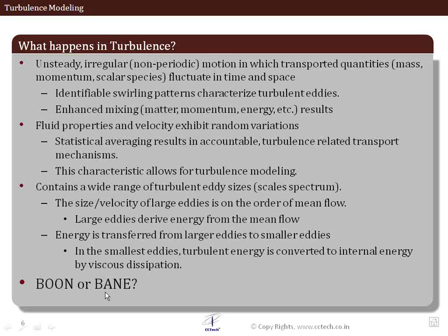So let's say flow is entering into a piping structure, and we want enhanced turbulence to cause efficient heat transfer. The cost we have to pay is that the duty on the pump, or let's say a compressor which is attached at the beginning of the piping structure, is increased because it has to provide higher pressure to cause the same amount of mass to flow within the domain. So the cost is the pressure drop, which is increased because of turbulence.